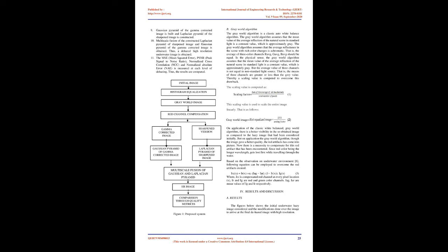With all this in mind, several software algorithms have been proposed in order to make the underwater image haze-free. One traditional and commonly used method to dehaze the image is histogram equalization [3]. The paper describes the utilization of adaptive histogram equalization to defog the captured image. Histogram equalization is a technique for adjusting image intensities to enhance the image contrast. It is the redistribution of the intensities of the image.